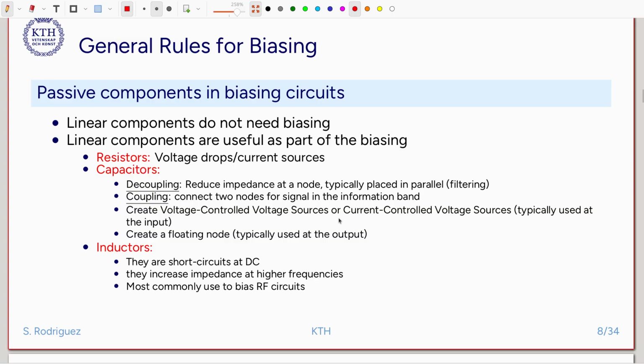For instance, let's see, we have an amplifier, a common source amplifier, and I can put a resistor as a load, and this resistor will let pass a current equal to the voltage across the resistor divided by the resistance. We call it the load resistor. Okay, so I can load this amplifier with this resistor and use it basically as a current source, so that this will be the current that passes here.